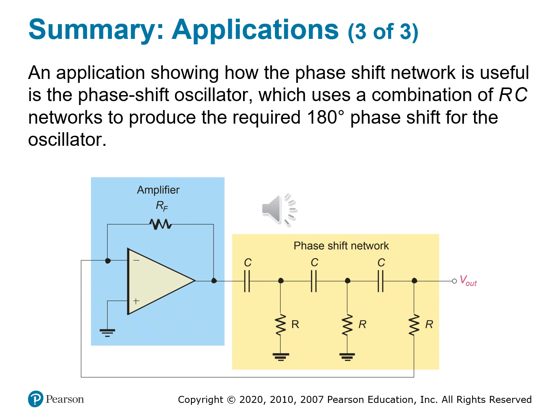Each RC pair adds roughly 60 degrees of lag, and you have 3 pairs, and that's where you get your full 180 degrees. The amplifier itself inverts another 180 degrees, and this brings it back to that full 360 degrees. Basically, it's like no net shift. So you have a 0 net shift because it's right back where it started, as far as feedback terms are concerned.